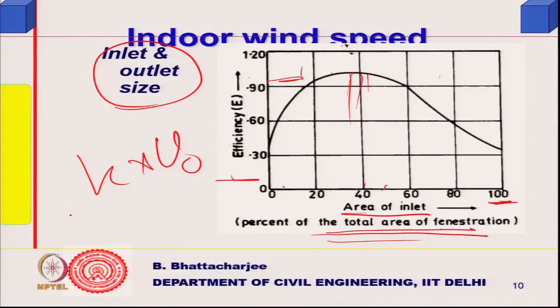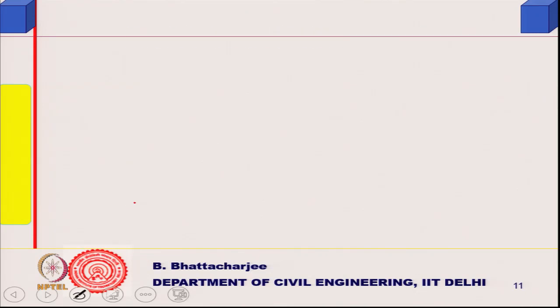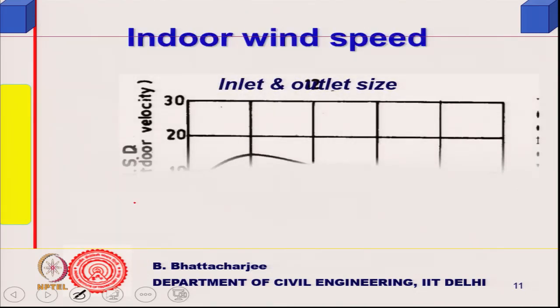In other words, something like this, if this is my slightly smaller window area. So, this inlet area, direction of window is like this, should be slightly smaller than outlet area, then it gets distributed better, average velocity is somewhat better. So, this gives you some idea how you do it, right.